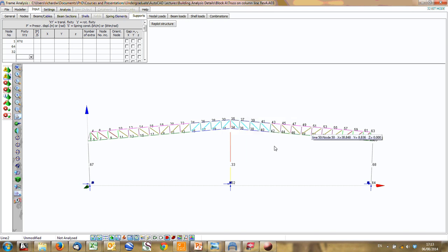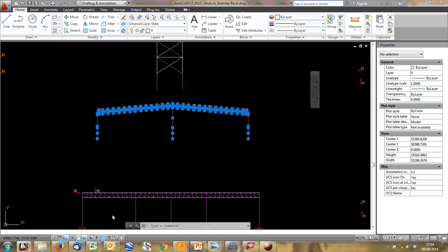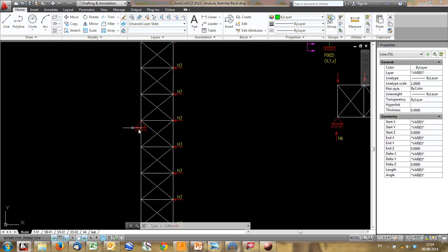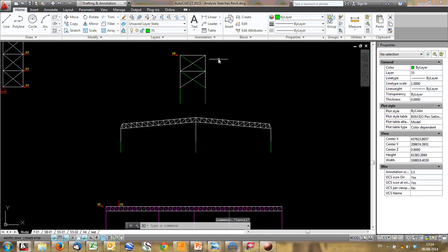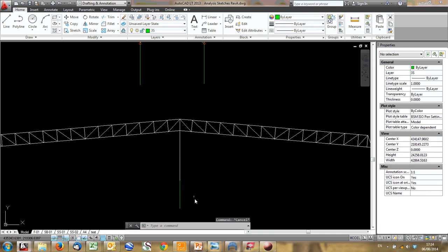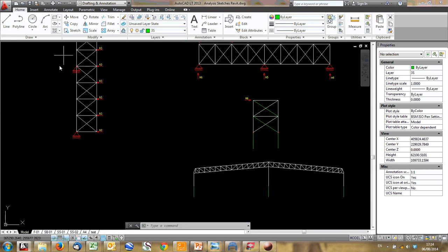Where the girder sits. This one is a bit more complicated to analyze because if this bay is much stiffer, it might actually act as a support for your horizontal bracing. So then this load you'd have to apply to this model here. If it's quite slender, then the roof bracing takes it all up. In structures especially, we've got big concrete columns that go all the way up, and you must design it. I'll try to show you an example just now of how you might do that. But then you'd have to apply all the reaction load here to this one and then design that for it.